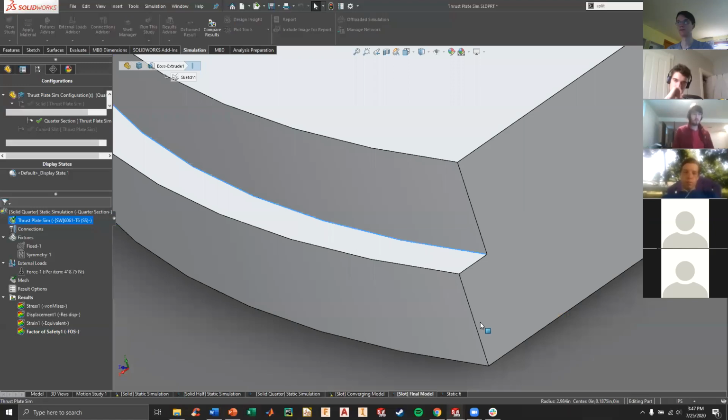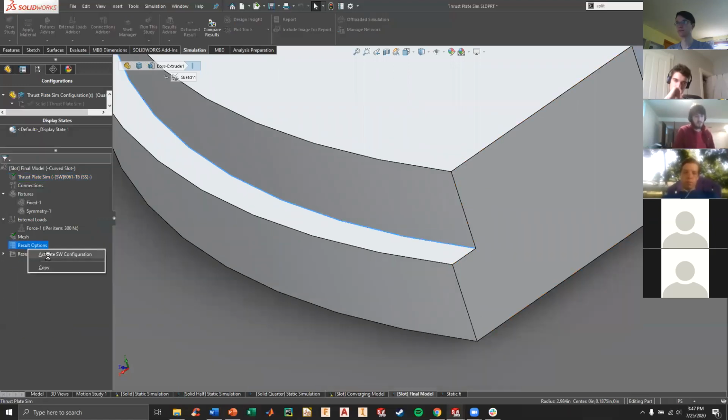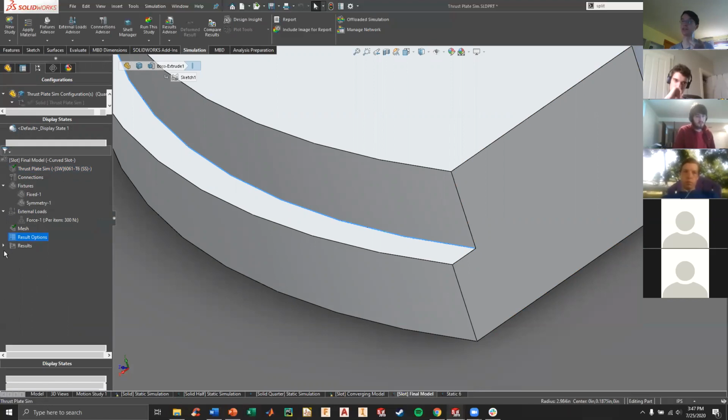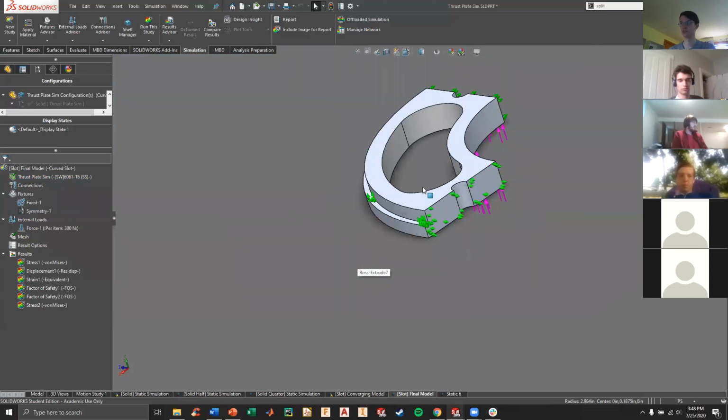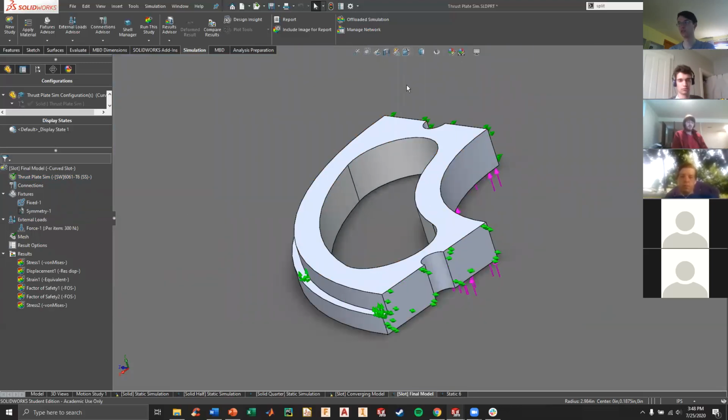But this is what happened to the de Havilland Comet. Yeah, so that was a stress concentration. So that was an actual same kind of shape. Yeah. So that's kind of where the issue comes in identifying whether it's a stress concentration or a singularity, and that's where the convergence plots help out a lot in being able to determine that. Because a stress concentration will eventually converge, particularly once you get into a mesh like I had. But this one was just increasing exponentially. So that's a singularity rather than a concentration.